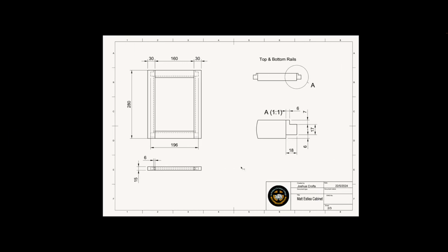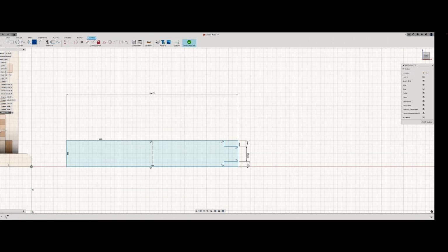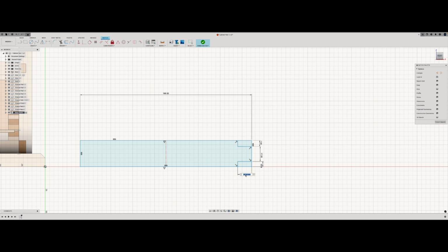And then we need to just take one last look at 6 and 18. So from this line here is 18. And then from here to here, because that top edge is shorter, should be 6. And that will move it that way. Now, what we can do is that's my whole tenon drawn. I can go through and select that line and hold shift, those 4 lines. I'm then going to mirror them around my mirror line, and I should end up with the same joint down this far end. Now, it all looks a bit funny at the moment, and that's okay.